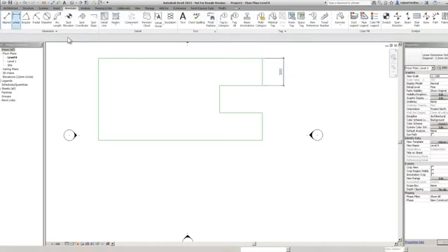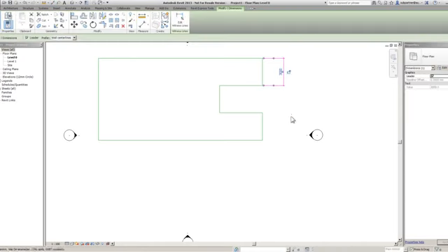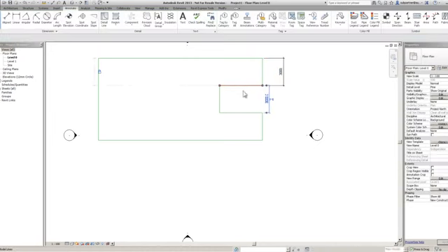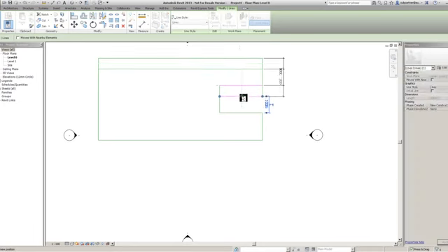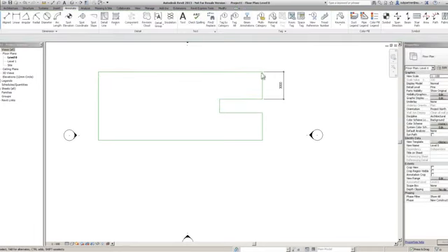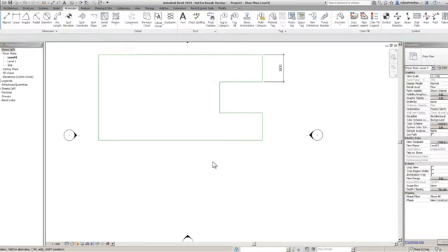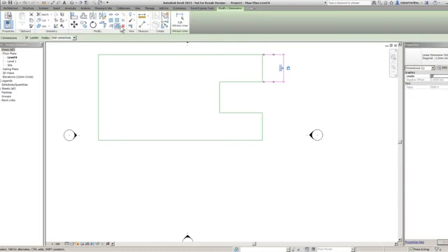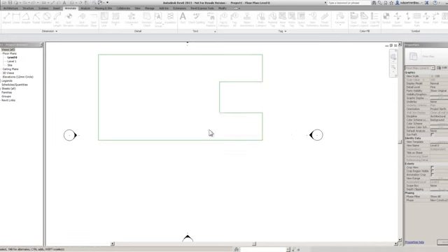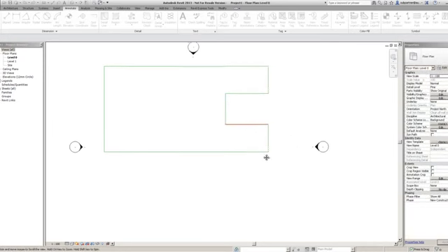Okay, hit modify. Now I'm going to select that and we see a little padlock symbol appear. If I lock it, watch what happens. I'm going to pick that line and pull it down. All it's doing is constraining the distance between those two lines. You see that? Nice and simple. Again, it works very similarly. If I delete it, it's going to come up with the same box. I'm going to unconstrain it this time just to keep my constraints off.